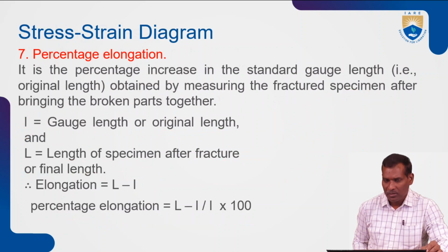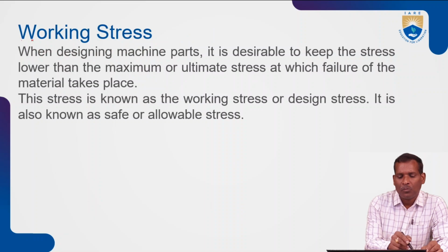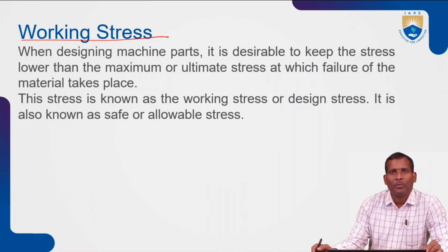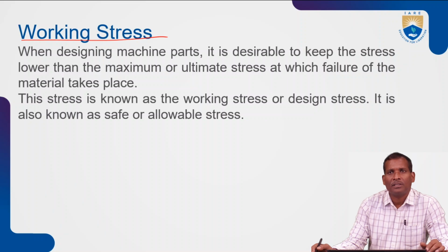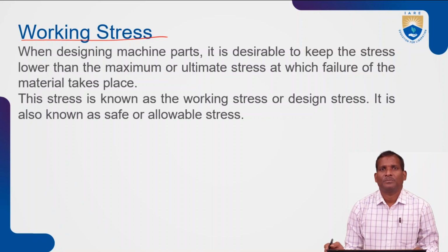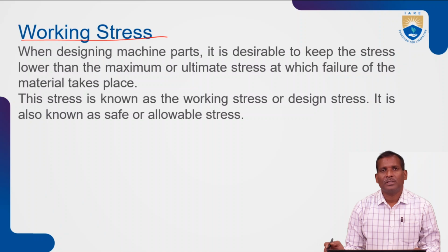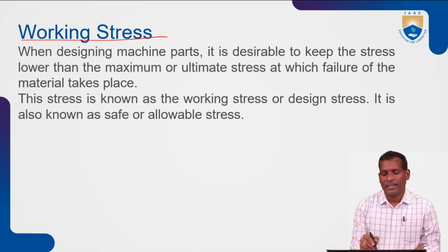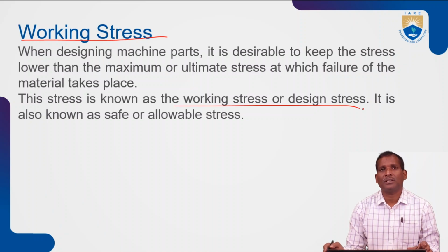Now we will discuss the working stress. When designing machine parts, it is desirable to keep the stress lower than the maximum or ultimate stress at which failure of the material takes place. This stress is known as the working stress, design stress or actual stress. It is also known as safe, allowable or permissible stress. So always it is desirable to keep the stress lower than the maximum or ultimate stress.